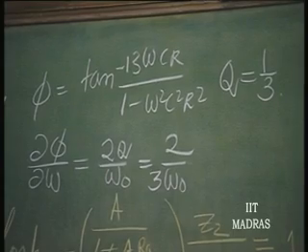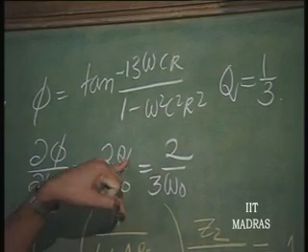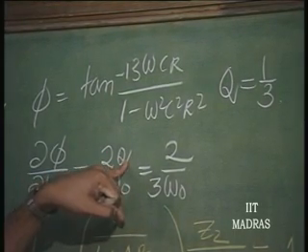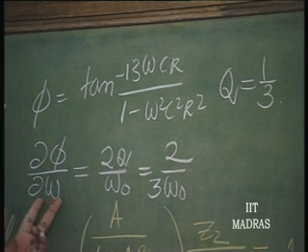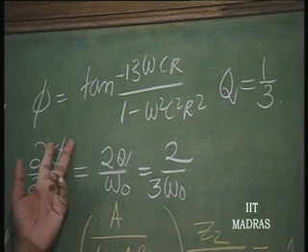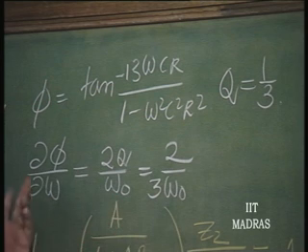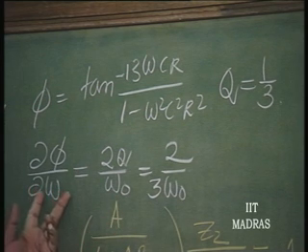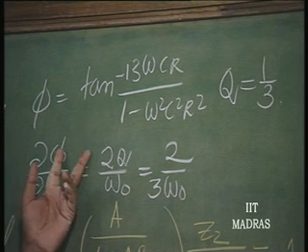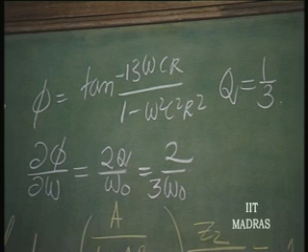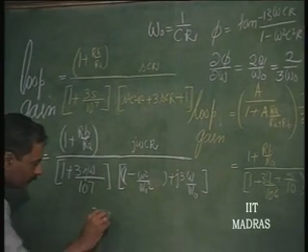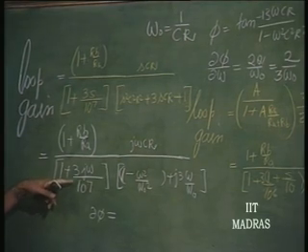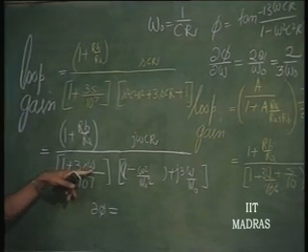Whereas in the previous example q was equal to 500. So, you could see that by a small change in frequency you could reach the required phase change. Here you require considerable change in frequency in order to have a particular phase change. What is the phase change required? Here the phase change delta phi required is straight away this when phi is small.